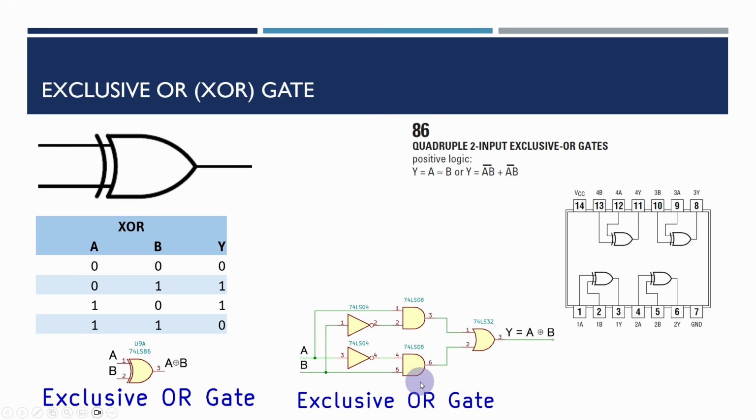But in a lot of cases, in the sort of projects I've been doing, a lot of these gates, we now use programmable logic devices, or PLDs, and we'll be talking about those once we've finished the next video. And there's a whole series on using programmable logic devices. These are chips, a similar sort of size, but we can actually program all the logic rules such that rather than needing 3 or 4 chips, or in this case, rather than needing 3 chips to do this, we could actually program the programmable logic device to do the exclusive OR without needing to have any other chips. We could also do things like ANDs, NANDs, NORs and things like that in the same chip without needing to have multiple chips when we perhaps only want one gate. So we'll have a look at the exclusive OR now.